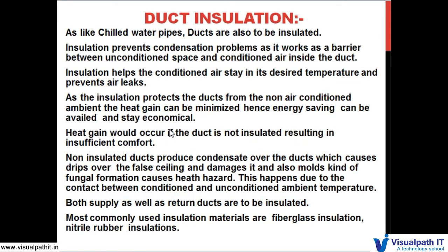The next important point we saw here is, as the insulation protects the ducts from the non-air conditioned space, the heat gain can be minimized. If it is not insulated, then the chilled air will come into contact with the non-air conditioned space, and there will be a heat gain, which makes the AHU run continuously to throw the chilled air to the space continuously, which will bring a high electricity bill.